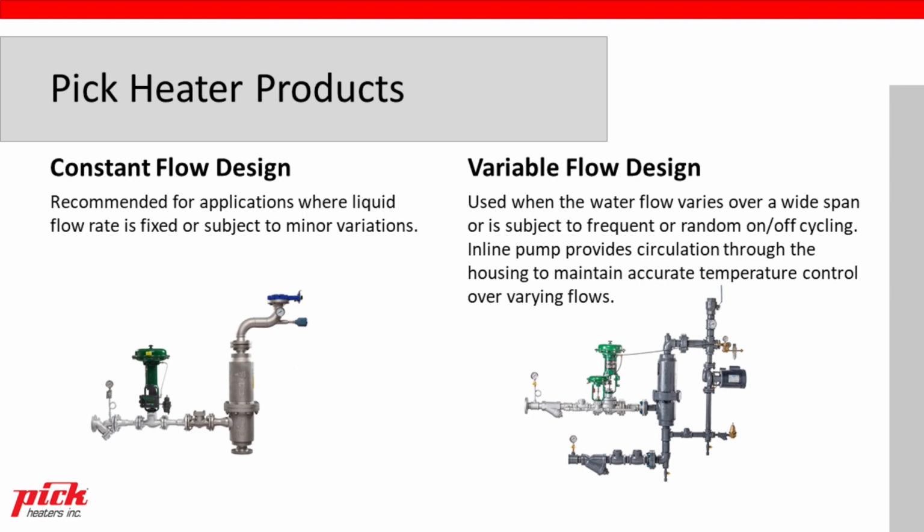Another type of product available is the variable flow design. That's used when the water flow varies over a wide span or is subjected to frequent or random on-off cycling. So if you're filling tanks on and off, or you're heating water for hoses or plant sanitation, that's going to be a continuously varying flow rate.